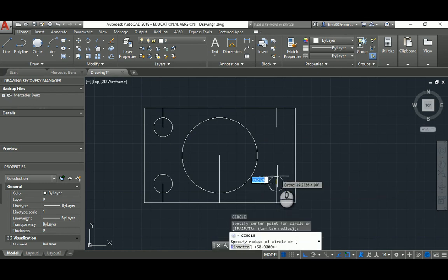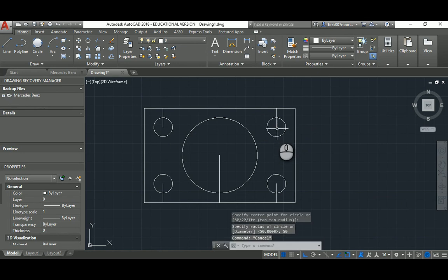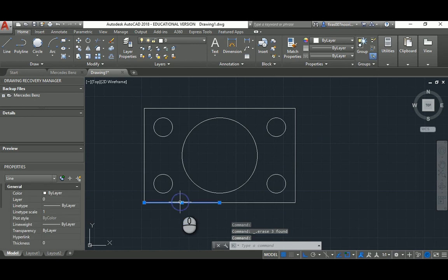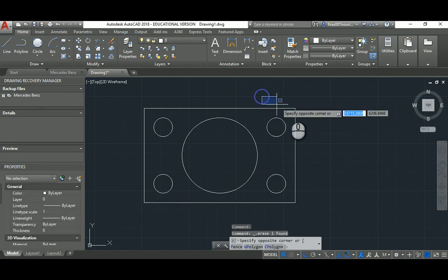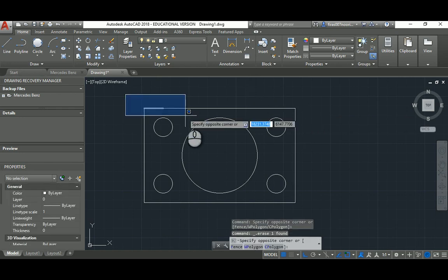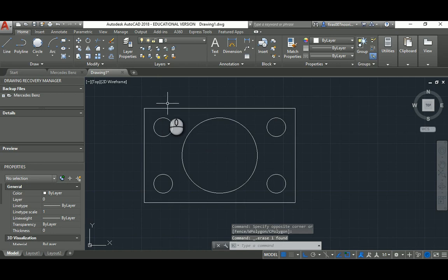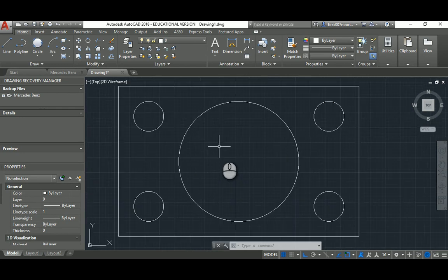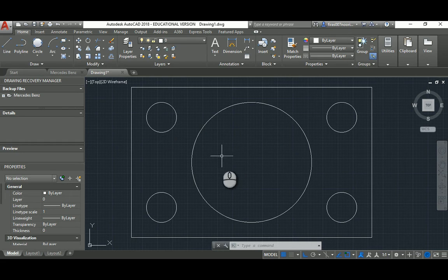This exercise shouldn't take more than 1 or 2 minutes of your time, and after you finish, it's a good idea to select and delete all the objects that I call construction lines, because you built them just for the sake of doing this job, and then you need to get rid of them. Now there will be 1 line, 2 lines, 3 here, 4, 5. If you hover the mouse above them, you can see it's highlighted for you. Click and delete again, click and delete, or you can use a window like this. When you go from the left to the right, it won't select the big one because it has to be contained all inside. That's the second exercise I think we've done. We've done the angle one before. So let's say that's our first exercise for this part of the lecture today.